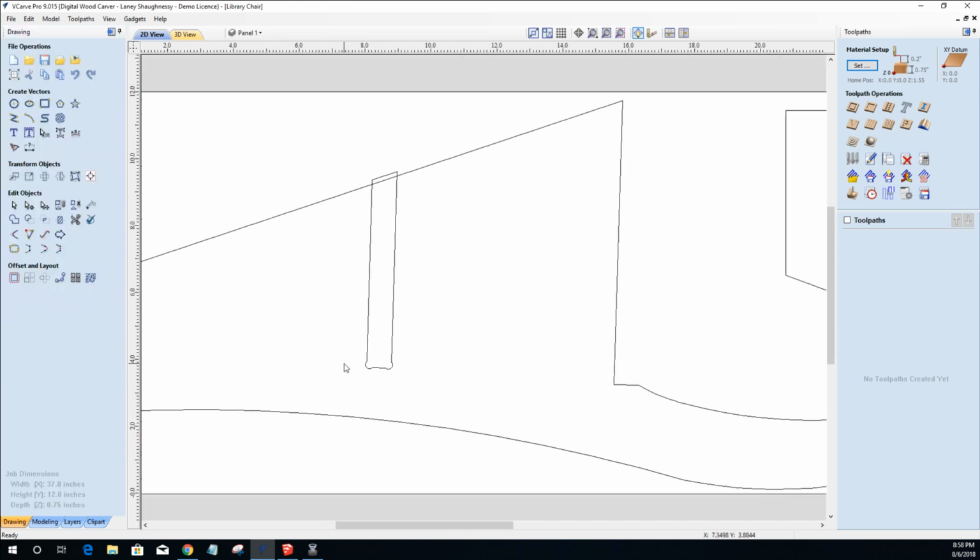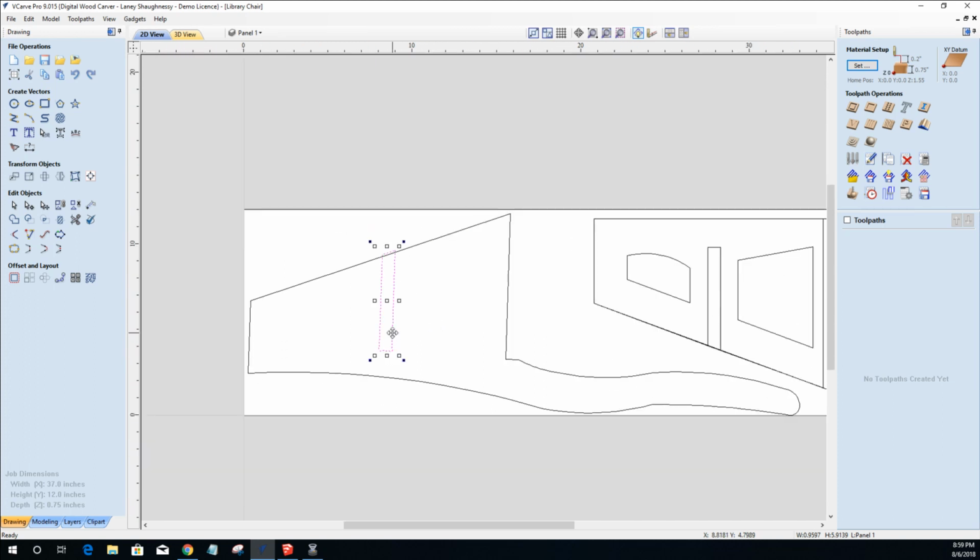That way I don't have to square off my step board. I can just cut it on a table saw. I can tilt my blade to 70 degrees or 20 degrees, however you want to look at it, and chop it off and cut it down to its final size. And I will have a cut list.